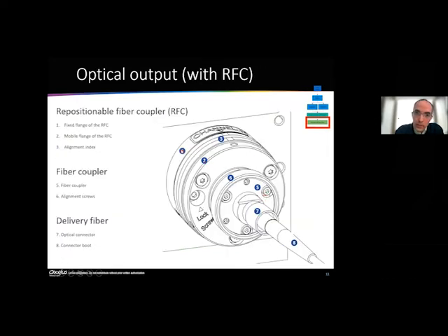These are two flanges facing each other, fixed together using magnets, and you can remove the mobile flange. You remove the whole coupling system, and you can put it back against the fixed flange, and you will not have to sustain important loss of power or redo your alignment.